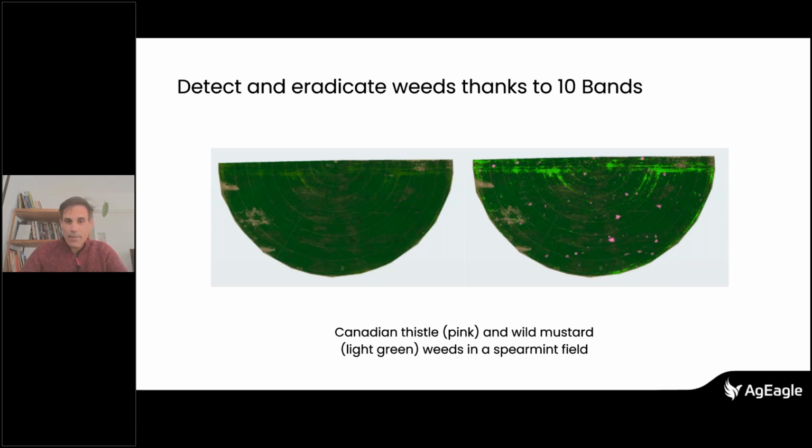And if you want to make a solution for yourself, you can also do so. I refer to the MicaSense user manual, where it is explained exactly which pin outputs are needed and how the configurations must be set in order to receive the RTK data into the camera and write these to the EXIF file of each of the images.